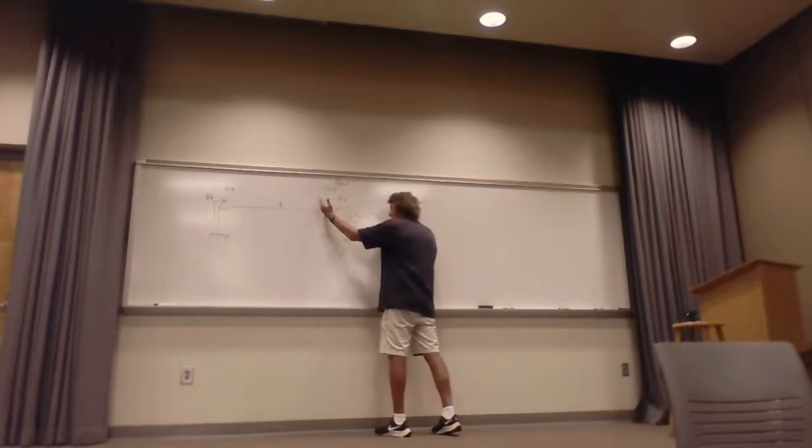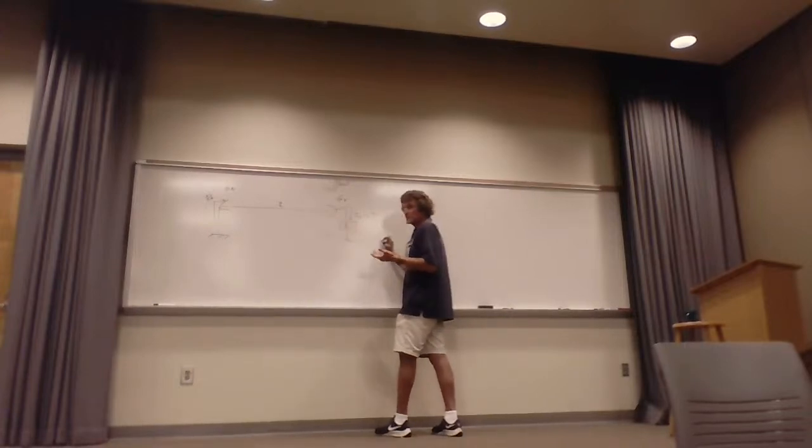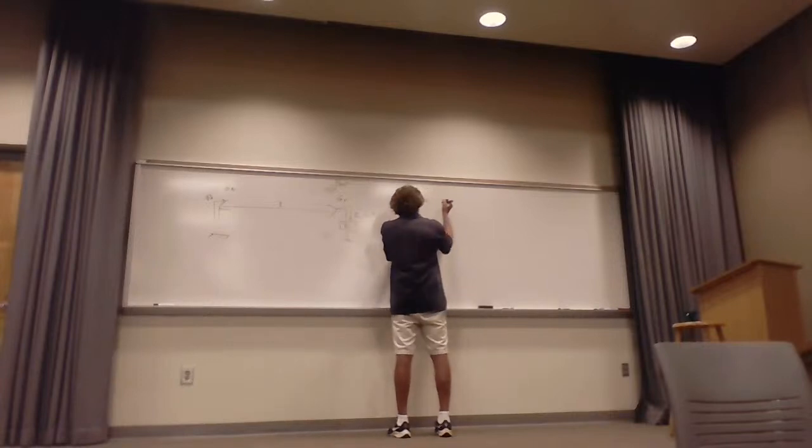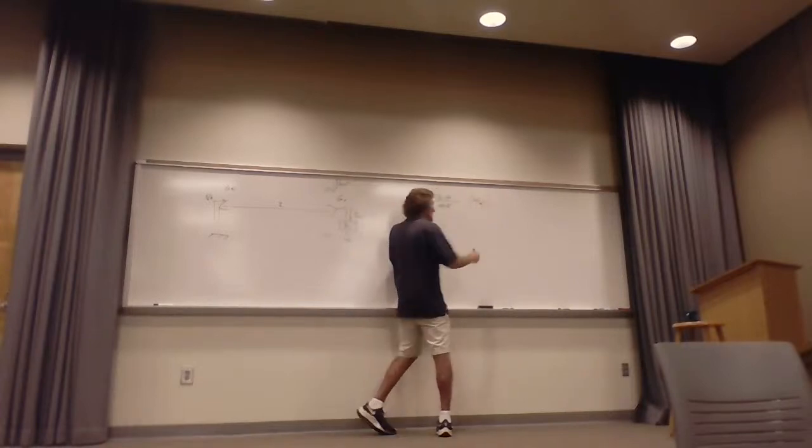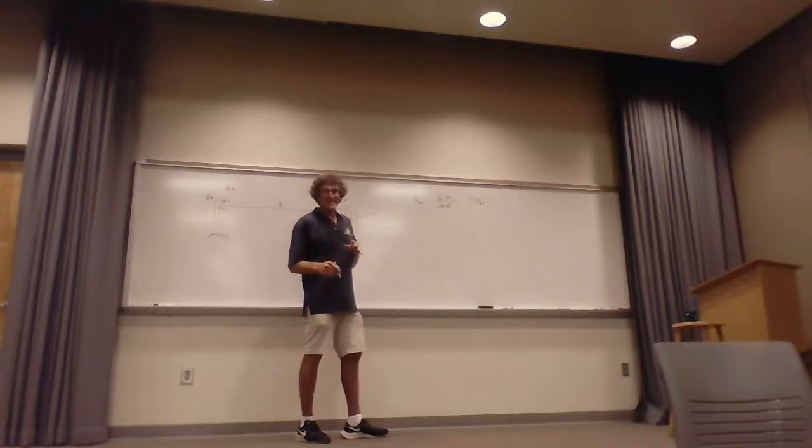You should know how to get the electric field strength there if it's air. The power density would be the transmitted power times the transmitter gain, which may be a function of angle, over 4 pi r squared, in watts per meter squared. That's the impinging power density.